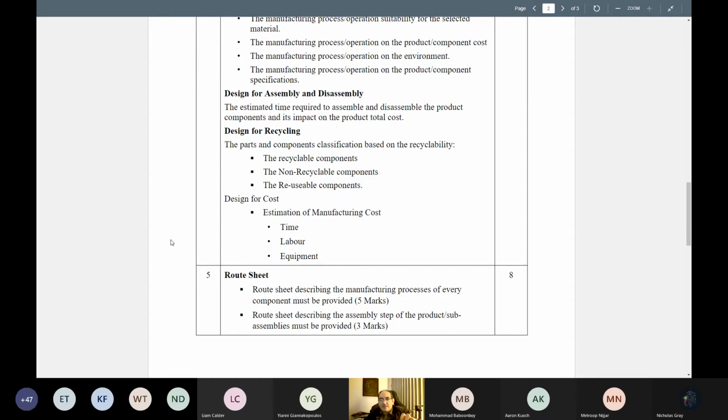Simply, this can be inspected. How do you inspect whether the PVC material still has the same properties or has been damaged? Do you have an idea on that? Usually you hold the tube and press it with your hand. If it cracks, that means it has lost its properties. That's easy.